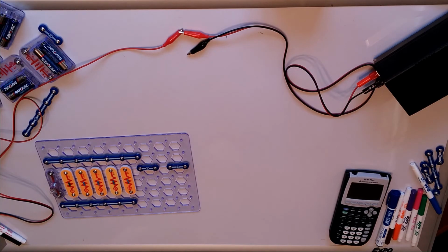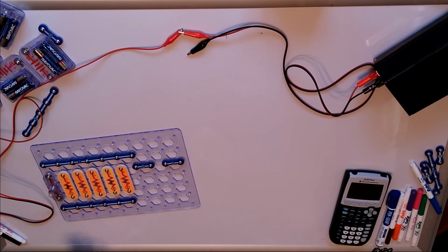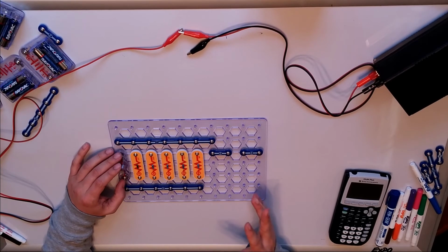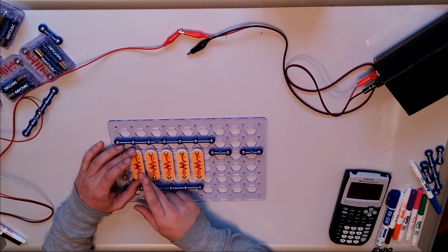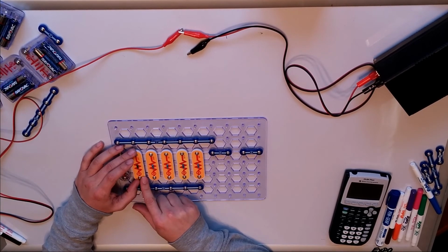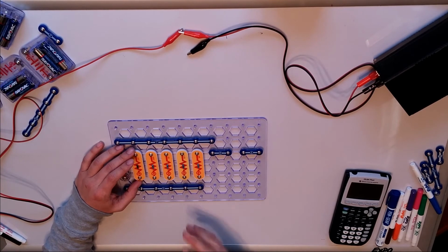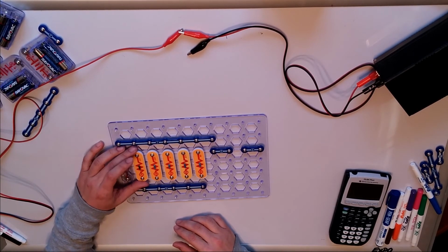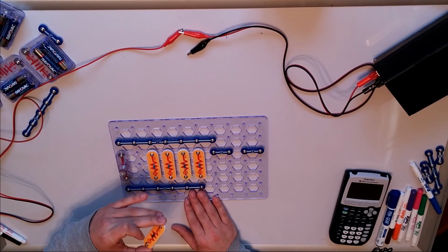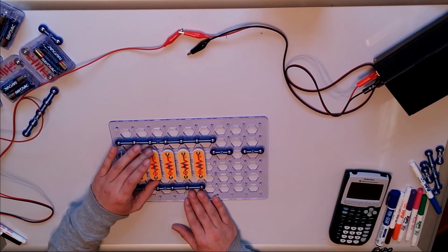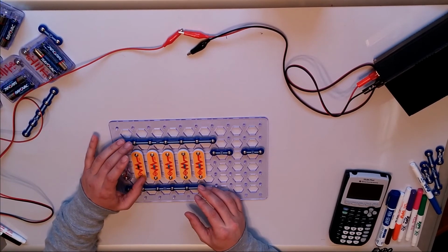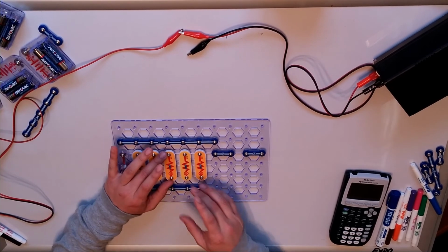Okay, so finishing up on what we just saw. We went over and we looked at the data. Again, we had the light bulb. We got that at about maybe 35 ohms or so. The 10 ohm resistor, R7, we got at about 13 ohms, but I'm pretty certain I can actually tell that part of it has melted. I think I subjected it to a little too much. Anyway, our 100 ohm, we were a little bit off. We got about 109, though that's still pretty close to our value.